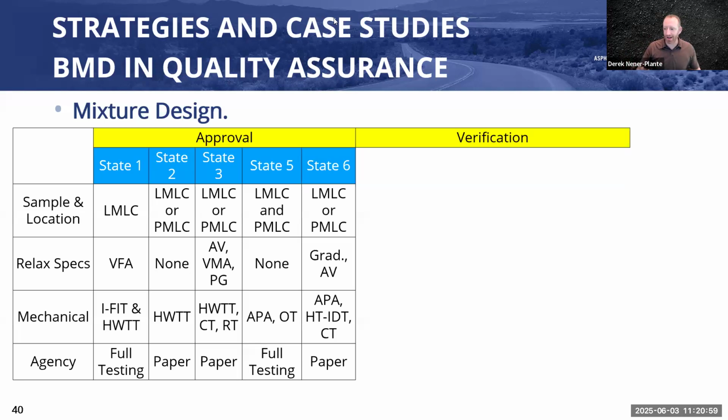Much of the work, it's not necessarily conclusive, but much of the work is showing that the difference between reheating a box after a day versus reheating it after 2 weeks or something, yeah, some have seen the differences, but the real big one that we know exists is between taking a specimen or taking a sample and compacting it within a half an hour versus letting it cool down and reheating it back up. That's the big difference we know we're going to have to account for in some way, shape, or form, or acknowledge it in your program and how you're thinking about it.